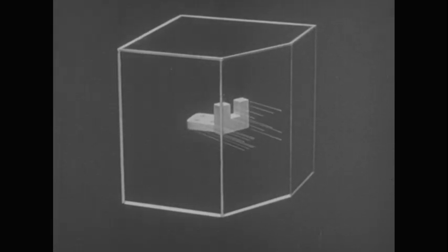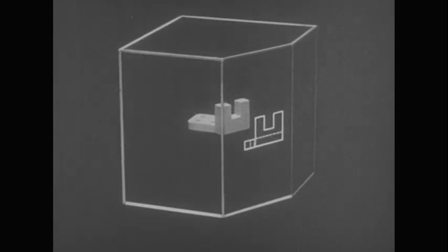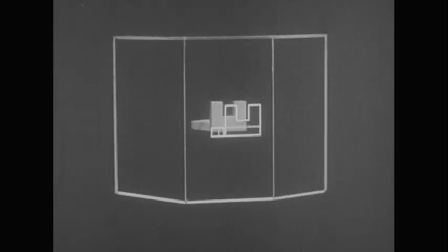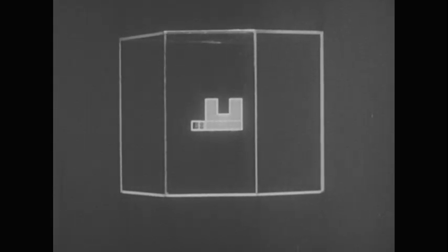Call the view projected on this auxiliary plane an auxiliary view. The auxiliary view will show the true shape of the slanting surface. Since you do not need the entire view, but only the slanting face, you can disregard the rest of the view. Call this a partial auxiliary.